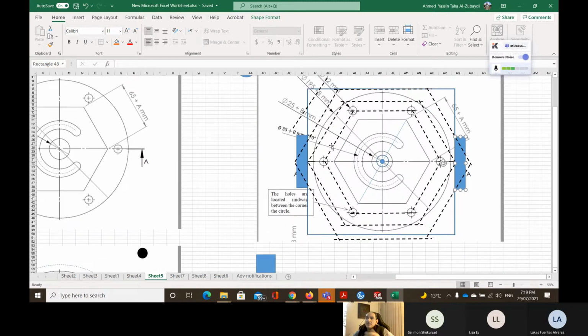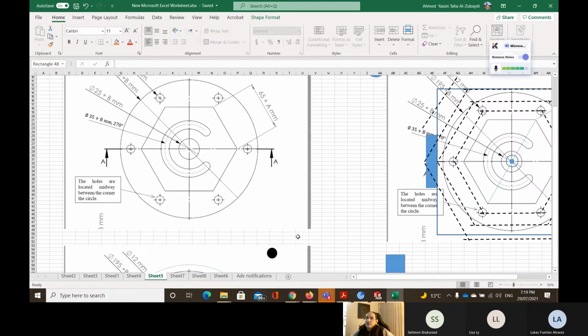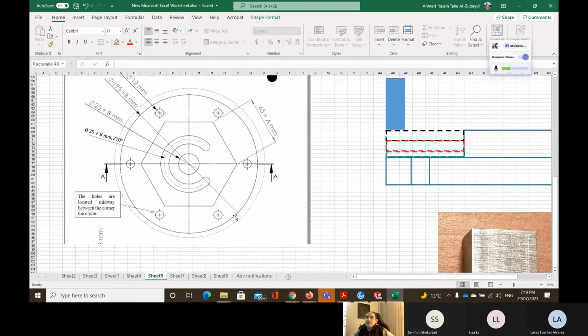Because we are going to have the holes, we are going to put it on the table using the T nuts, which are going to be sliding in the T slots we have on the table of the CNC. And we're going to have at least 2 to 3 bolts fixed, for example, here, here, and here to fix the work part on the table. We put a layer of protective plywood, for example, beneath it to protect the table. Then we start to do the cutting around.